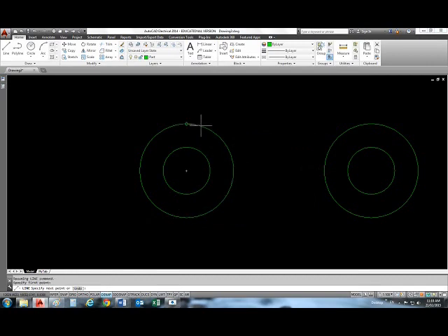So click here and then type at 75, 0, enter, at 0, minus 25.4, enter, at 50, 0, enter, at 0, 25.4, enter. And then I could go to the top of the circle, make sure that the snap point is clear, and click, and then escape or enter or spacebar.